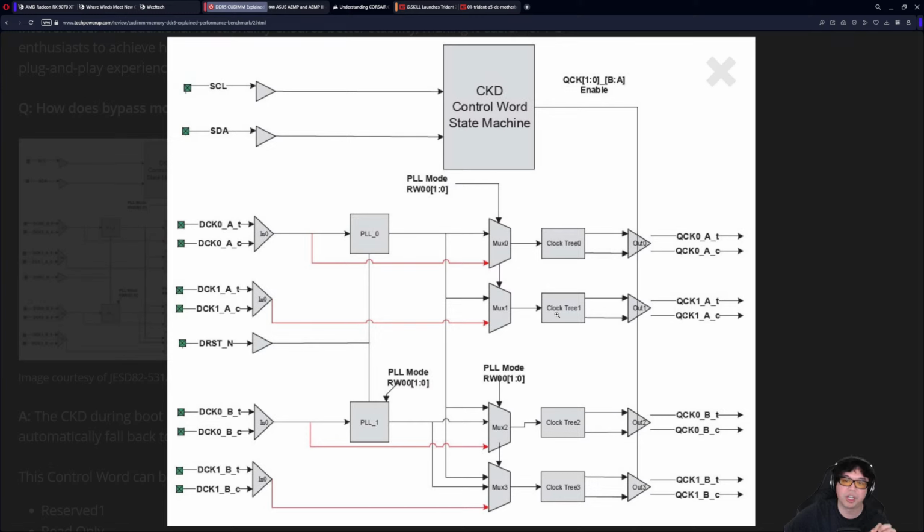It cannot train. I let it train for 35 minutes of memory training, and it eventually stalls out with the orange light. It never progresses past, I think, code 7F or something. It gets stuck at like 7F or 18, and it never progresses. I let it sit for 35 minutes of memory training on Intel, and it refused to train.